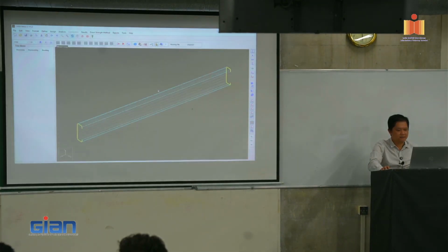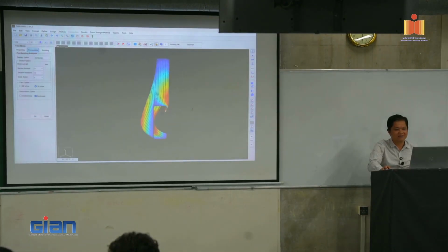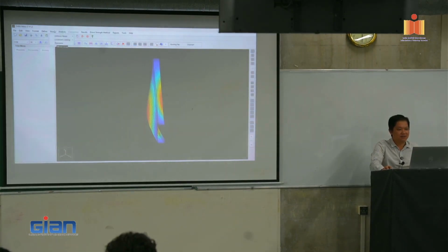Okay, it's done. Good. So you can see if I click here, it's still there. Okay, you can see that. Now that line is straight, right? But the bottom plate, from how you press it, is buckled out. So I'm going to stop the bottom plate as well. You can see the pure localized loading. Okay, so we unlock it and we put another restraint on that.